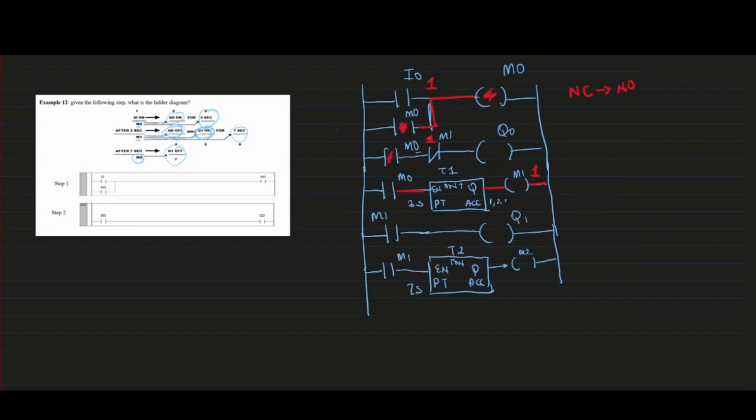Now, what M2 does is effectively trip off the entire circuit. So in order to trip off the entire circuit, I'm just going to add it to the first circuit, because the second this first circuit is turned off, nothing in this machine will be on again. So to model a stop signal again, we add it as a normally closed signal M2.